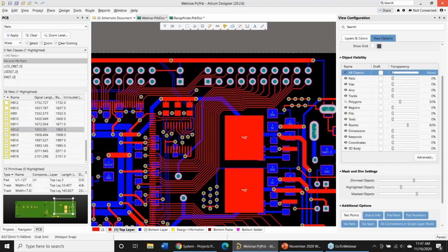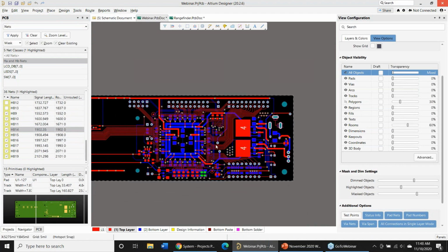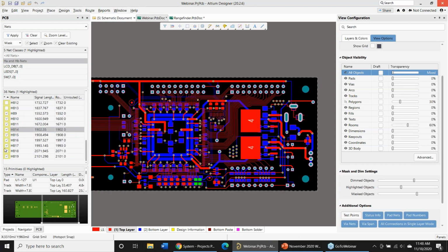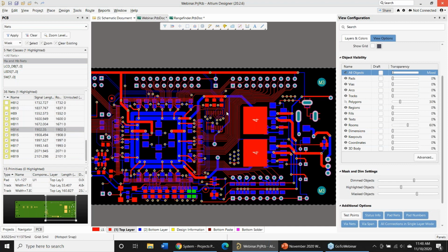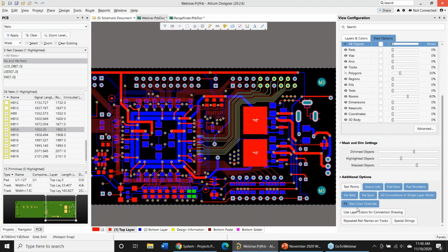Now you don't see it yet because Altium does something nice, because of course color is important in the PCB. You don't want to create red colors here because that's going to conflict with your red colors on your layer. So I can hit the F5 key, and if you look down here, F5 is the net color override. So I'm just hitting the F5 key. I can turn colors on, turn them off. Some people like to use colors, especially for power nets and things like that.